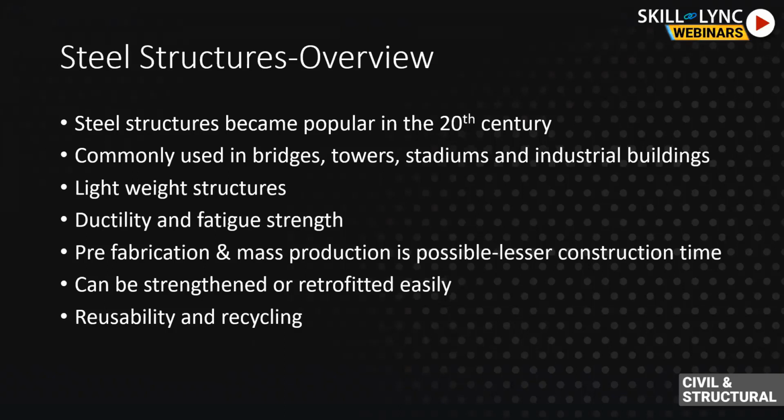If you have a 1 inch, that is a 25 mm, steel rod, it can hang almost 20,000 kg or 20 tons of weight. That is almost equivalent to 4 elephants. So that is the strength of steel compared to its weight. That is the greatest advantage of having steel structures for large spans. In concrete, you may be going for a 3 to 6 meter span, but in steel structures, you can see around 30 meters, 40 meters without an intermediate column.